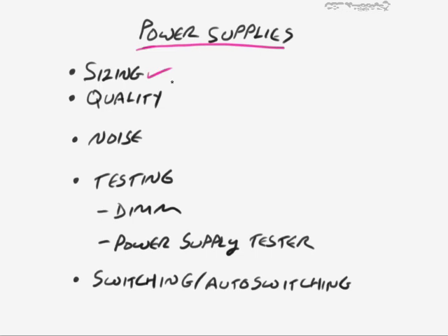If you're not familiar with a Y splitter, what happens with those is, if this is my power supply and out of the back of this is a connector for serial ATA power, for example. I'll just kind of put a block on that. If I've only got one, but I need 2, then you just get a Y splitter, and it will put 2 different additional connectors on there. The problem with that is you can start to daisy chain too many of those together, and it can generate heat on this line and can stress the power supply. So just got to be a little bit aware of that. But anyway, a lot of the manufacturers right now, or at least some of them, are only giving you the bare minimum that you need and maybe one additional one.